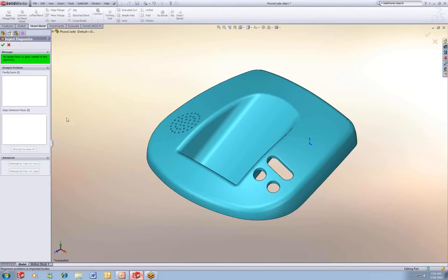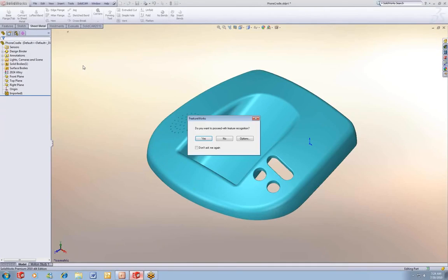And to be honest, I got lucky here. This was a file type that a customer sent me, and it looks very clean, and I don't have any issues. Where you run into issues is, if you're doing any mold design, or even fixture design like I'm going to show here, if there are any broken faces, broken edges, it potentially makes that process a lot longer. And the worse the model, the longer it's going to take you. So just a couple things there.